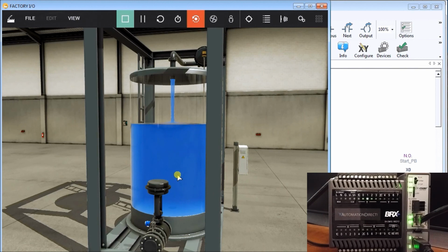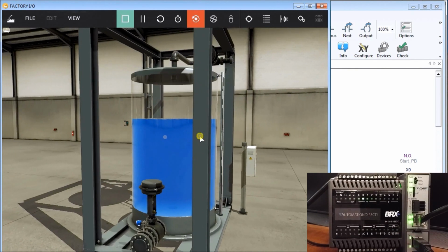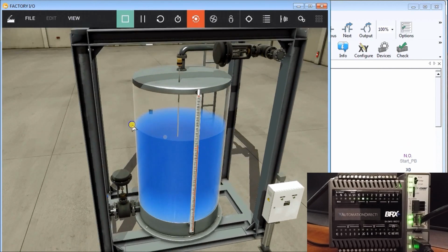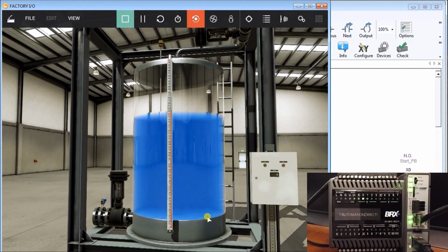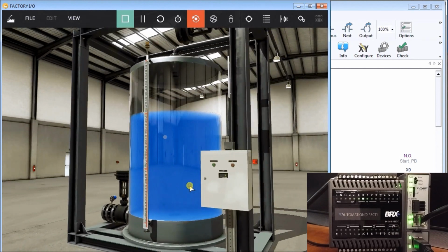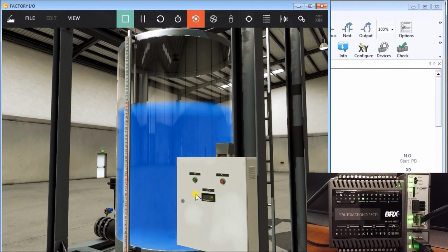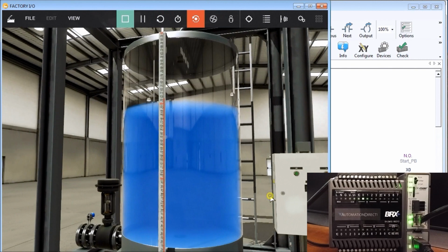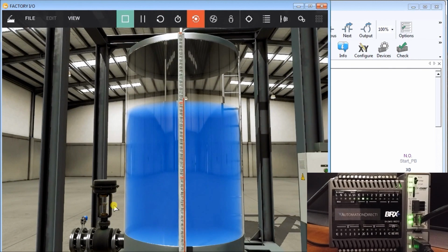So we're filling up, and you'll see it's going to reach that top sensor soon. It's going to stop off that input to fill it up. There you go. And we'll swing around, and now we should see the dwell timer starting to time. Sure, there's 15 seconds. At the same time, we could be monitoring our actual logic like we did before and view this. Now after the 30 seconds, which is really close, what you'll see is this valve now will open up, and we will actually then start emptying that tank.